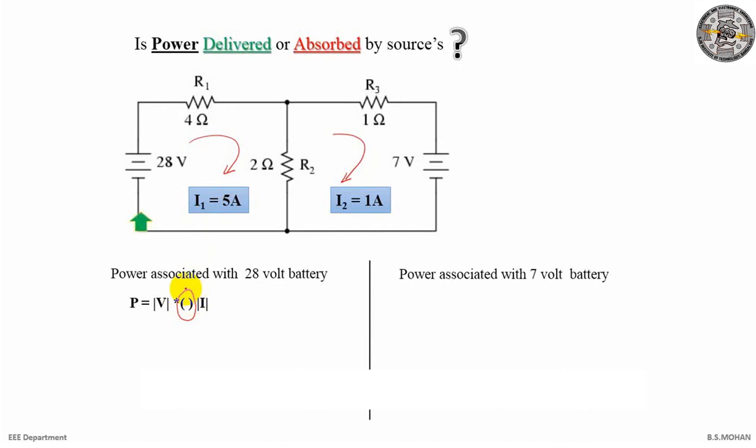Now as we apply the currents in clockwise direction, mesh 1 current I1 travels upward through this branch. That means the current I1 travels through 4 ohm and then 2 ohm, and then it travels through 28 volts. It hits negative polarity first. So then how do we incorporate this negative sign, or what is the equation for this voltage? As you can see in the equation here, I have written the modulus, that is the magnitude of voltage and magnitude of current.